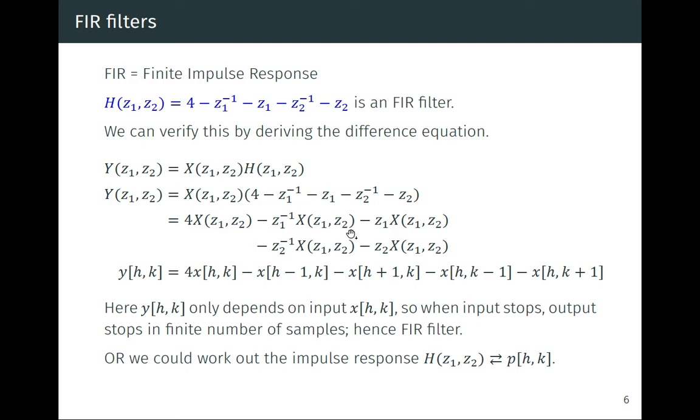Basically, to come back to your discrete domain, you only need to know the inverse z transform of this monomial times x. When you do this, the exponent z to the minus 1 would just add a minus 1 to all the exponents, but what you're doing here is shifting by plus 1, so there will actually be this term here. Have I lost you here? Okay, I'll just do that again.